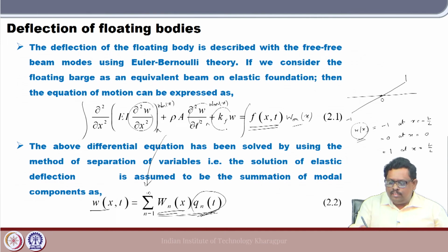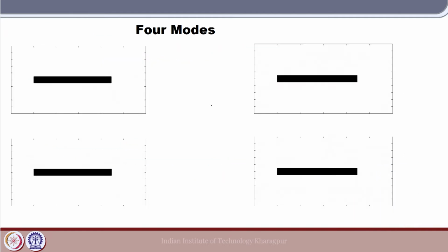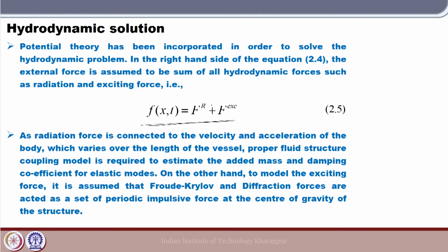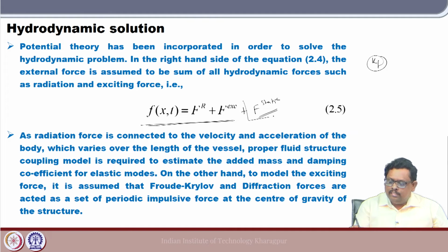That means, in this Kf actually we are writing the hydrostatic component. Okay. But it is not necessary, you can still ignore it, and you can still write here as F static also, you can do that. So, it is not that strict a restriction that you have to write everything in the stiffness matrix, that is in the Kf only, not necessary. That hydrostatic part you can incorporate in the right hand side, and you can treat it as an external force.